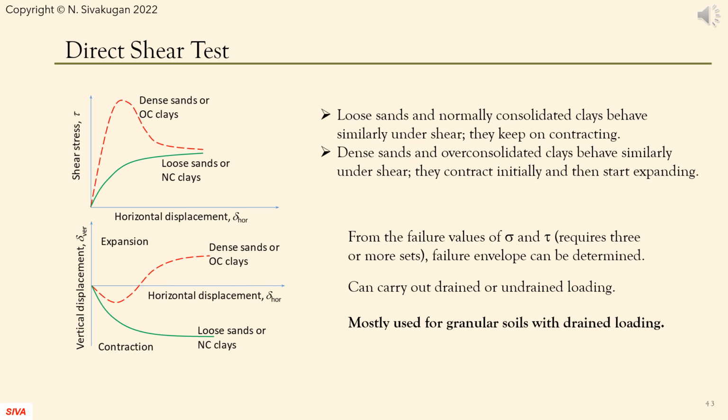Loose granular soils and normally consolidated clays behave similarly. They keep compressing until they fail. Dense granular soils and over-consolidated clays show similar behavior when loaded. They compress initially and then expand.